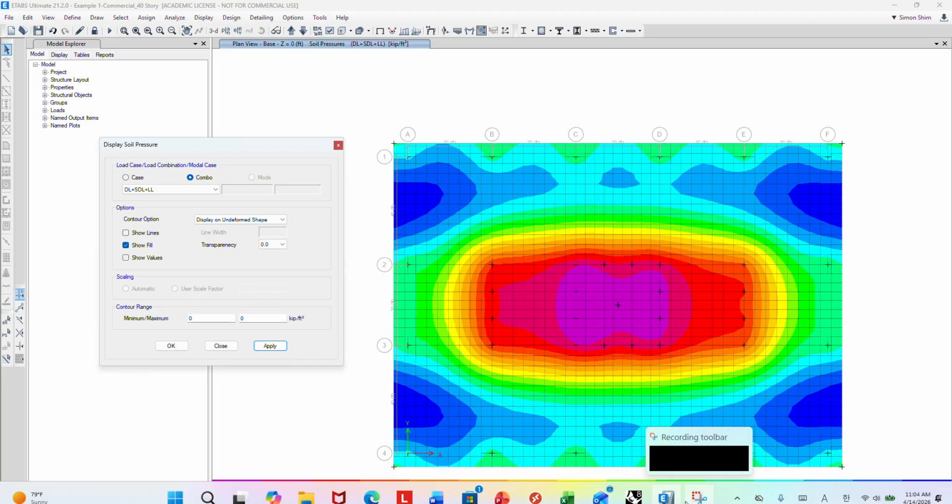which gives you the required area of the footing, right? If you choose your footing size, assume that we already did it. You draw it, size it. So total dead, SDL and live load divided by the mat area, you can roughly calculate the soil bearing stress. But because this is a small scale, you assume uniform distribution. So basically, you don't differentiate the stress gradation. Basically, total dead plus live load divided by area. So you say all the loading is uniformly pressed down. That is your footing design philosophy.